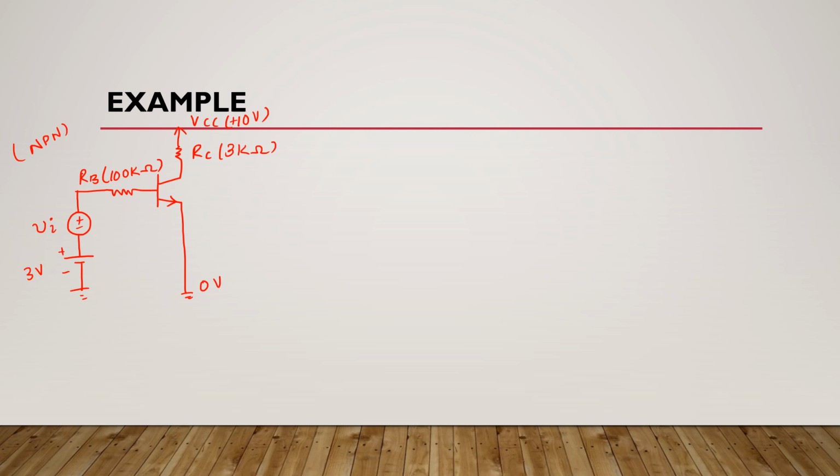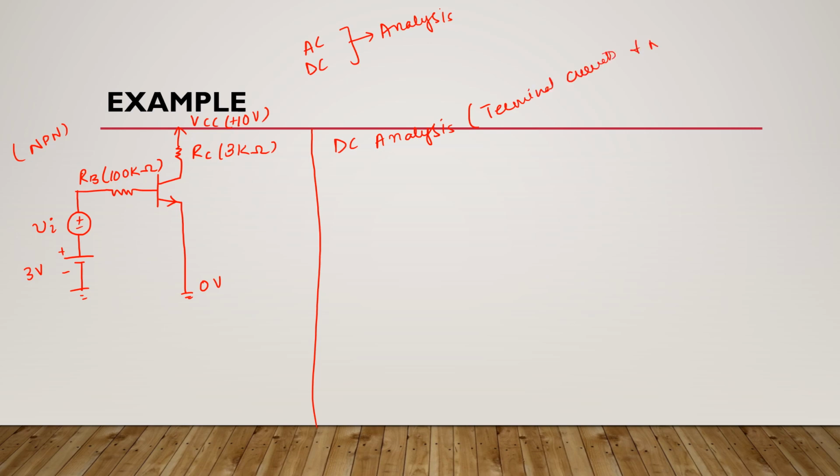You have to perform both AC and DC analysis here. So how are you going to solve this circuit? First we will perform DC analysis. We know that in DC analysis we find all terminal currents and nodal voltages.